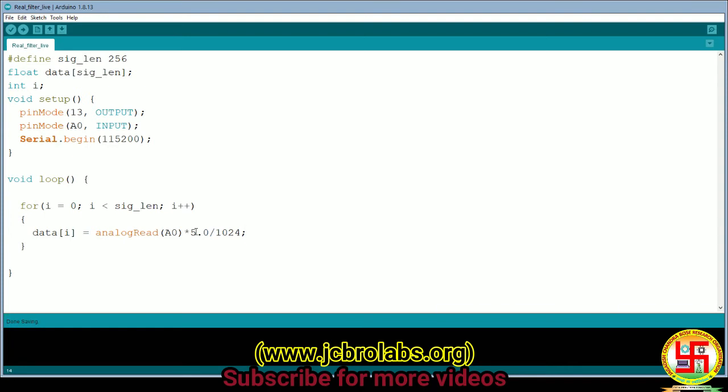Remember, this Arduino can only get the data from 0 to plus 5 volts, right? So your function generator should have some offset, so all the waveforms should be above 0 volts, and the same you might have seen during the setup portion. That means the waveform coming from the function generator was above 0. Okay, so we have set it.